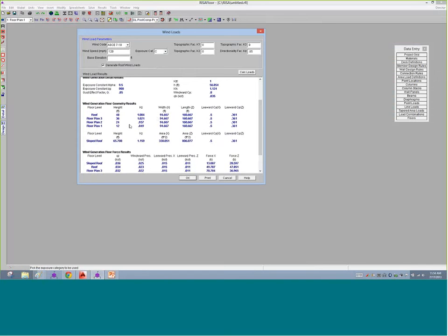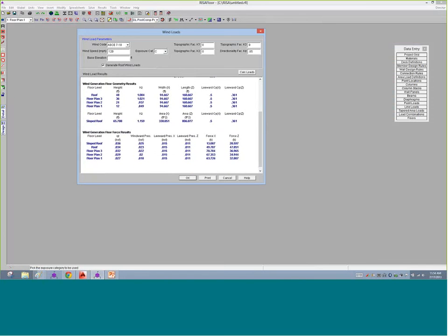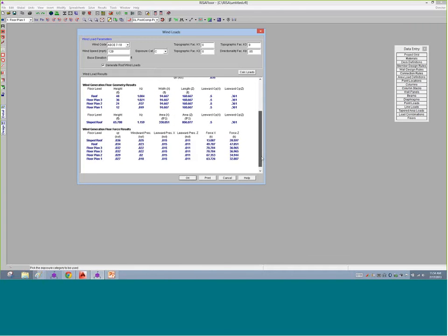Now, as I mentioned, you can tell the program you're going to be using a flexible or a rigid diaphragm, but no matter what, you're going to get one point load in the X and the Z direction, and we're going to transfer that into the structure. So we'll see here that the sloped roof gets a portion of that, the rest of the structure gets a portion of those loads in the X and the Z direction, and we can see it graphically. If I'm designing the structure, I would typically print this spreadsheet and have this for my design calculations, and go from there into RISA 3D.